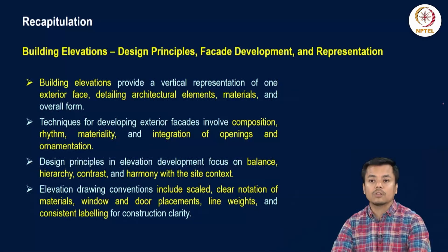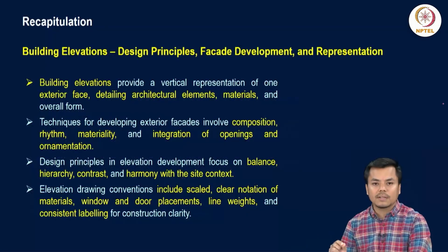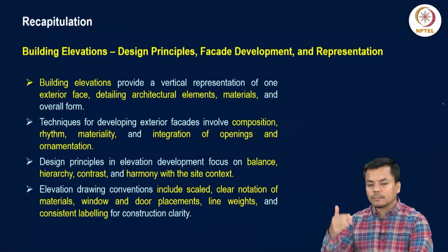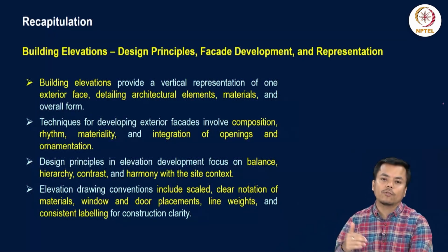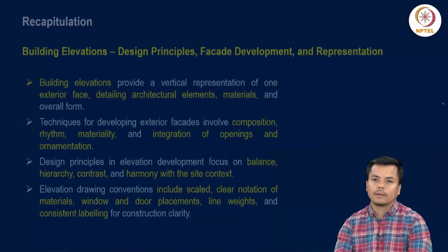Elevation drawing conventions include scaled clear notation of material, window and door placement, line weights, and consistent labeling of the drawing. So all the dimensions, all the details about the elements that are being used, and also through line weight and the color or the shadow pattern, all information can reflect the various details about the elevation that you have drafted.